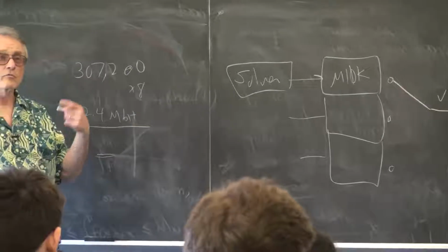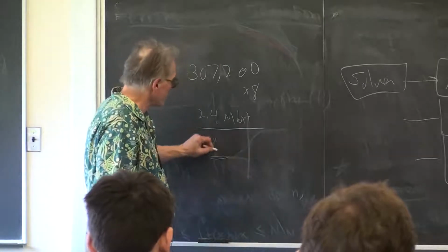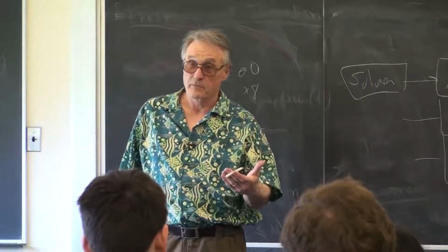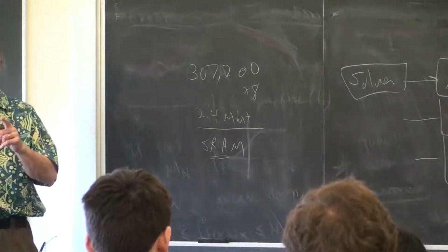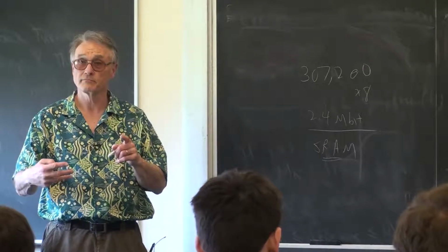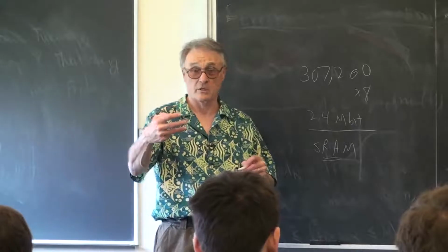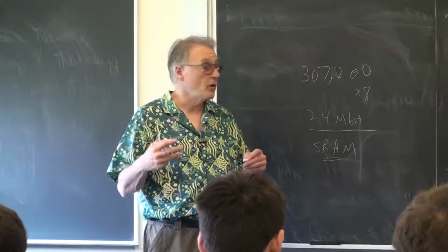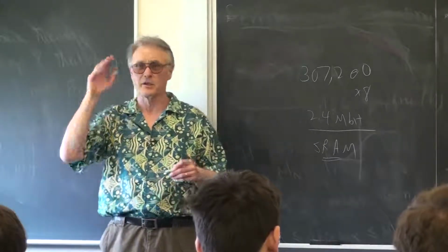So it is possible to do this. Now you have your own write port on the onboard SRAM. There should be no limit to how fast you could write it aside from the state machine. So the SRAM lives on QSYS. It has 2 ports. One port is hooked to the VGA controller. The other port is shared between your bus masters. And that might be a good intermediate way of using QSYS while maintaining a high write rate. Because now you have no contention between your bus masters and the VGA controller, which is the other big bus user. The HPS is just sitting there doing nothing at this point.